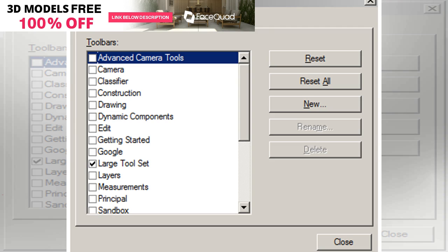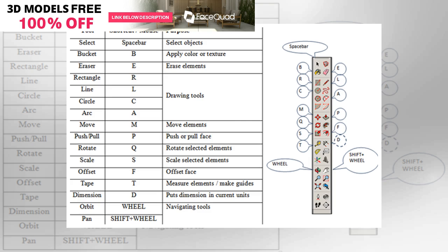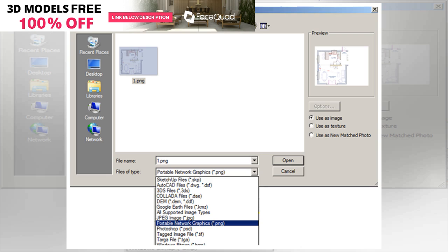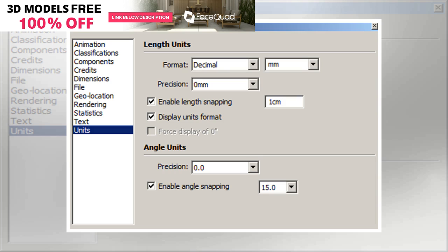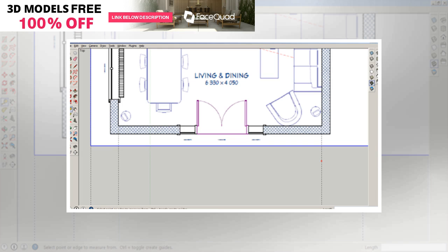Now, let's protect the floor plan from any occasional changes. Right-click, Explode, double-click on Face, right-click, Make Group, right-click, Lock. Now you are unable to edit the floor plan picture, and you don't need this. Time to draw lines. Use tools R, L, E to outline the exterior of the house. Use X-ray style, in Styles toolbox, to see the floor plan behind the shape you are drawing.